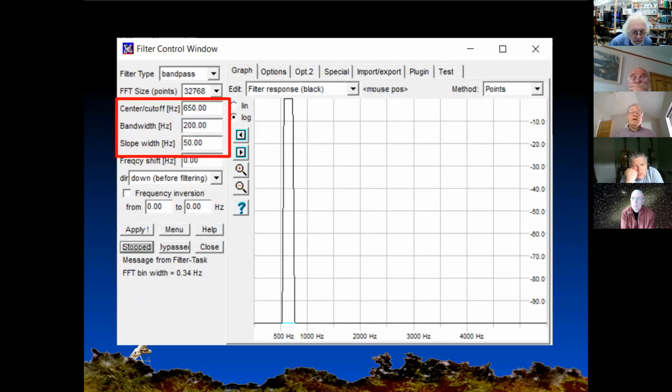You set up the frequency and width of the filter here. A lovely thing about filter design in the digital domain is you can do incredibly sharp cutoffs. What we're looking at is selecting the output of frequency bins. And we've already seen frequency bins can be less than 1 hertz wide. So you can get cutoffs that are just unimaginable with discrete components.